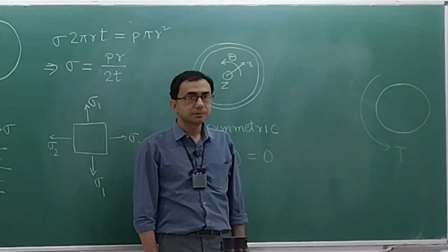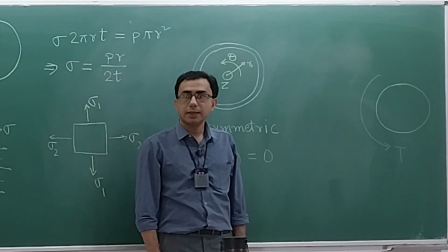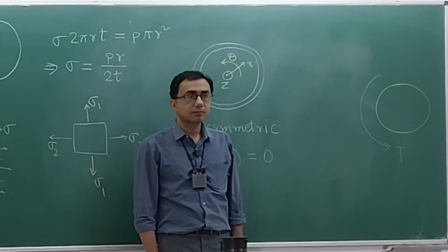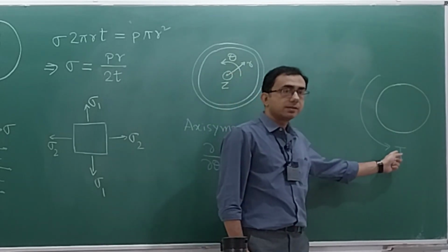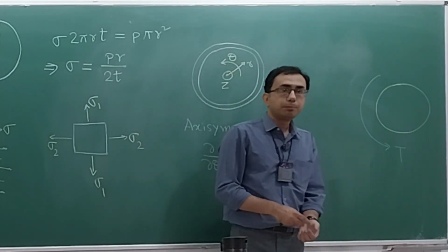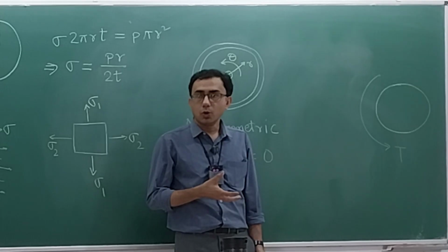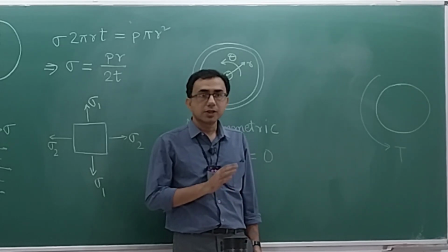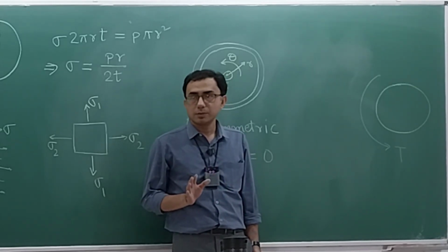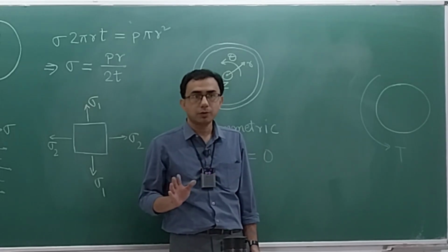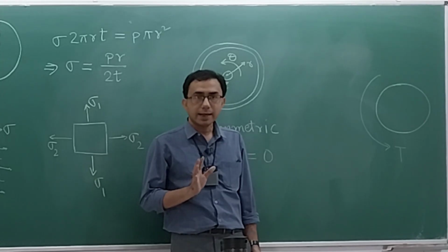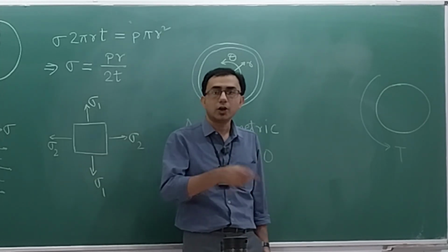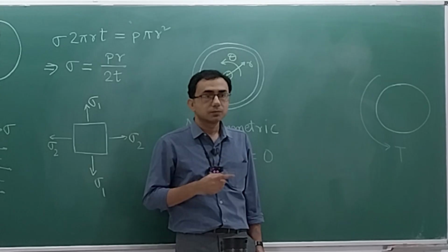You all agree, right? Does anyone not agree that this is axisymmetric? Please raise your hand confidently. Okay, this is very much axisymmetric. So the presence of a load in the theta direction does not preclude axisymmetry, as long as that load itself is not varying along the theta direction.